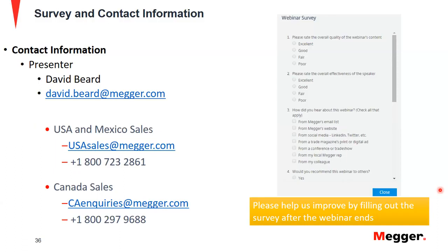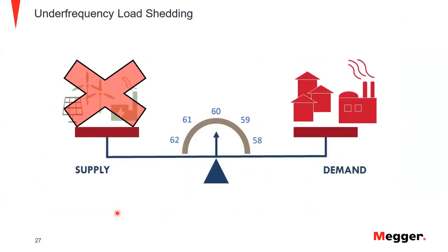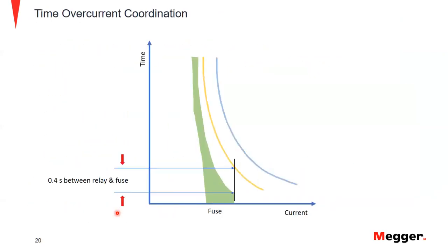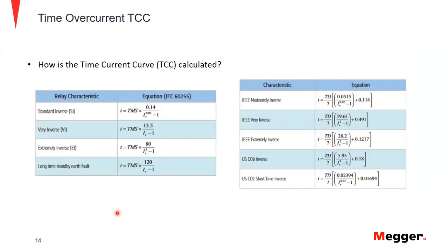Sugosh, David, if you would go to slide 14, I believe they were referring to that one when they asked this. How do I choose between these curves? What does it depend on? You would need to perform the short circuit and coordination studies, and then you could use these curves based on your studies in combination with the thermal capacity of the lines being protected.